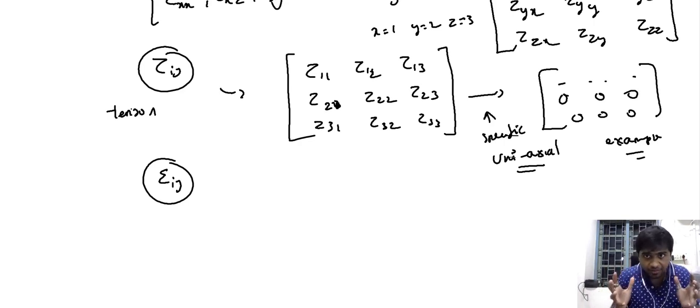So this stems from the components of stresses that are required to provide a comprehensive description for the stress, and these components of stress elegantly align themselves in the form of a matrix. The components of stresses are dependent on two indices, and that's the reason we have a specific shape for this matrix. Since the tensor representation of the stress is the most generalized one, and any theoretical model has to start off from a generalized description, stresses are treated as a tensor, and from that generalized description we will be able to apply it to any specific case.